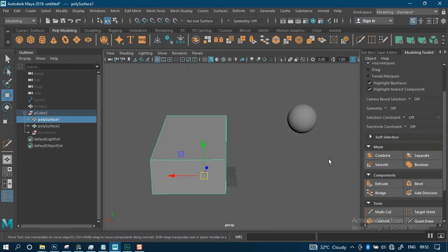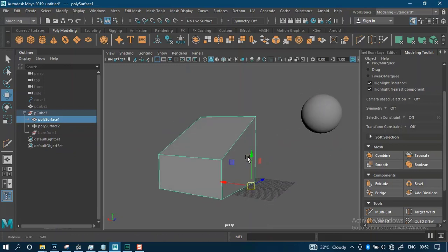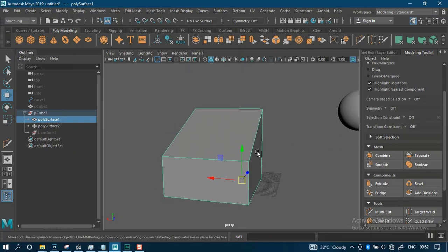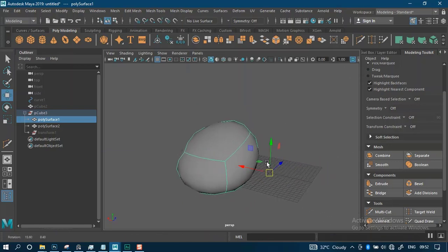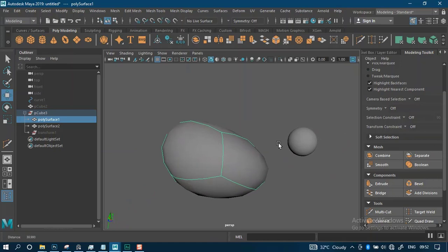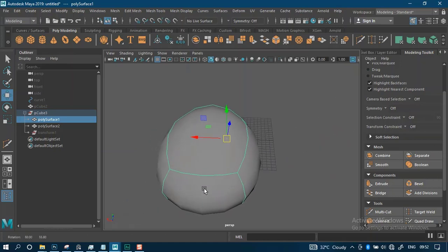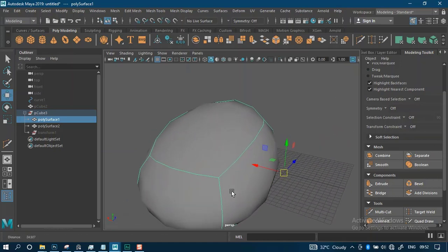And selecting this, one thing I need to mention. If you click on the 3 key on your keyboard, to go to auto smooth. So let's say I just hit 3 on the keyboard, just sending this to auto smooth. This is not actually applied directly on the surface as a subdivided mesh.